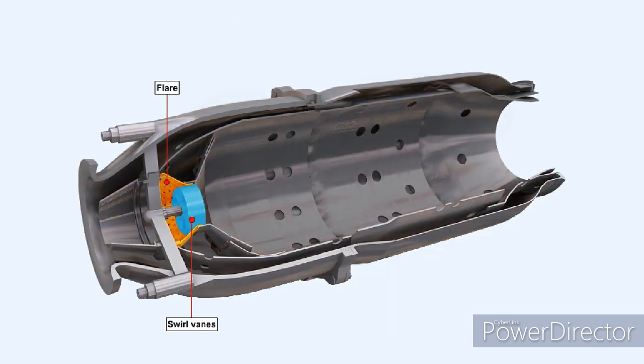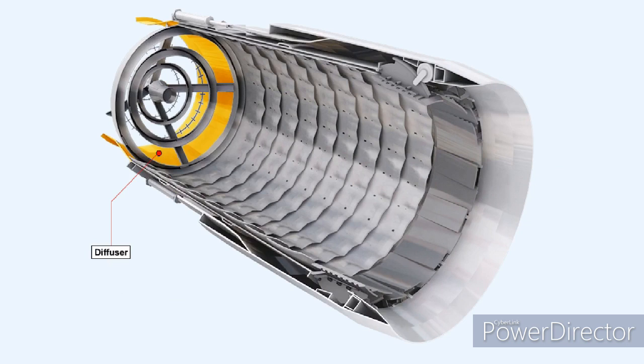In the combustion chambers lesson, we stated that because the flame rate of kerosene is only approximately 30 feet per second, to prevent the flame in the chamber being extinguished immediately, we had to slow down the speed of the air entering the combustion chamber. In the combustion chamber we used components called the flare and swirl vanes to effect that reduction in velocity. Because of this low flame rate, we must also reduce the velocity of the gas stream through the afterburner, in order that the afterburner flame can remain stable. This is achieved by a diffuser, which is positioned before the afterburner section.